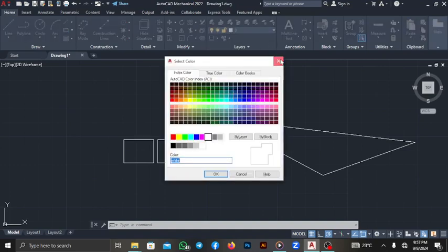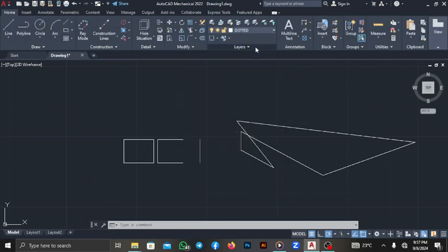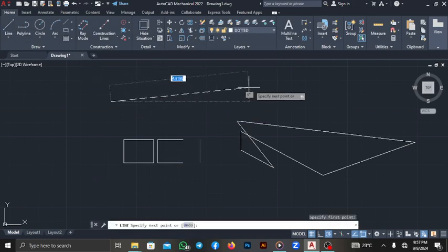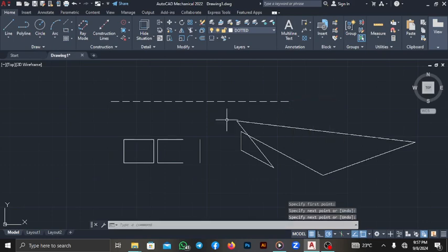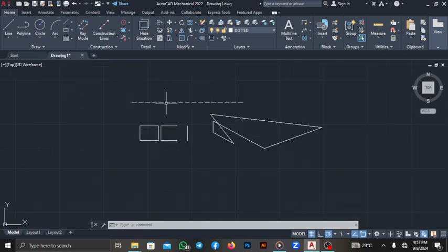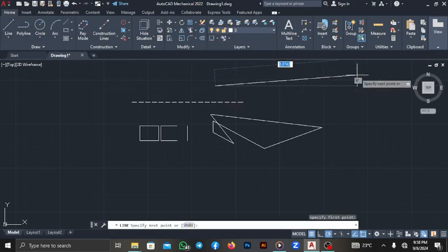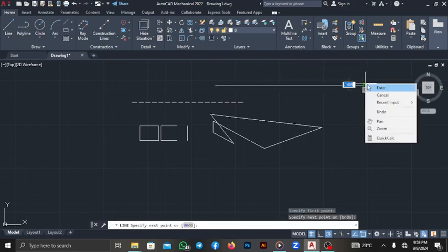Once you select it, and then we pick our line to draw, we click and then we extend, and we have broken lines coming out. Are we okay? So now what if, right after drawing these broken lines, I'm only using them for a part of my whole drawing but not a full drawing? To convert it back, all I need to do is move to the top, click the drop down and send it back to 0. Once it gets back to 0 and I draw a normal line, it becomes a continuous line.